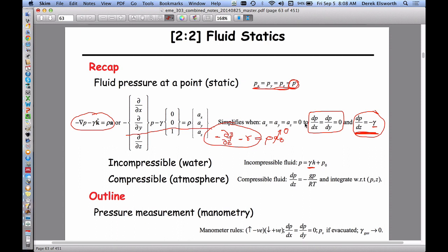And so that's what you might expect from a swimming pool. And I guess the corollary of that is that if you look at the surface of water, then that also has to be horizontal as well, because that has 0 pressure on it, atmospheric pressure acting on it. And so that has to follow the same rules. And so I guess this is kind of a consequence that liquids always come to some equilibrium horizontal arrangement. So if you're trying to put a foundation in for a house, one way to take level from one location to another is to get a big long piece of Tygon tube, which is clear, or a garden hose, fill it with water, and you know that the water level in the tube at this location on the foundation is exactly at the same elevation as the water level on this side.